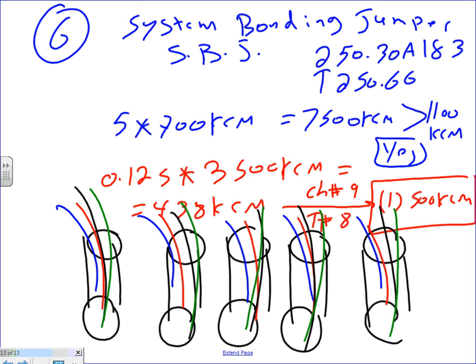5 sets of conduits. Each one of them is carrying 4 conductors, 3 phase and neutral. In my case, it's full neutral. Really you should derate it, but I just don't do the math. You guys are good at doing the math. You can take the 200 aside, cut everything higher than 200 by 75, and parallel 5 sets. I don't know if that was your answer, I'm just exaggerating here.